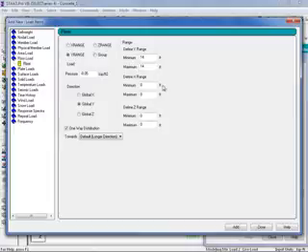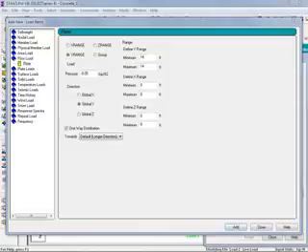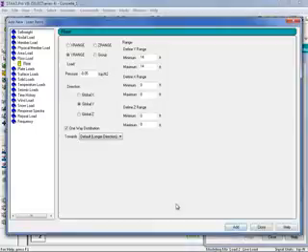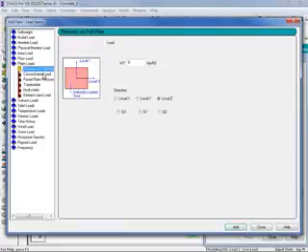Once you are done entering your floor load item, I can go ahead and click Add, and now I'm ready to apply more loads if they are applicable to the live load case. I'm also going to be applying some plate loads. So I'm going to go ahead and select the plate load option, and here you can see I have several different options of plate loads available, and I'm going to select just the pressure on full plate option. Again, I can just enter a magnitude. I'm going to enter negative 0.05 kips per square foot, and I'm going to go towards the global Y direction. But since this is a plate load, I also have the option to do the local axis as well.